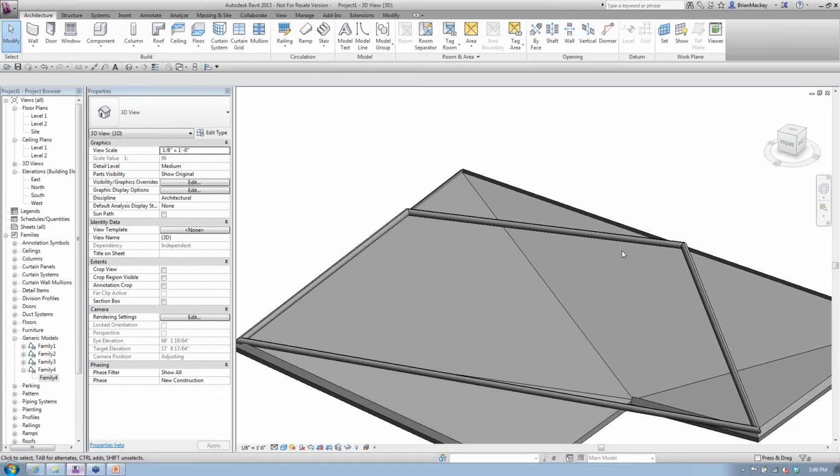It's one of those things, too, and with the 4 pick points, if it's a window with a different lintel and a different sill, as long as you've got pick points on there, you could just pick the 4 edges of the window. If it's a one or two off scenario, and not every window, just go through and host it in there.